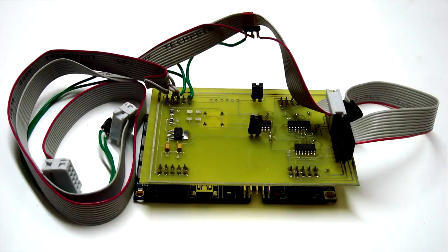Since I had an effective glitch, I took the circuit from the breadboard and etched a simple PCB that could plug directly onto the XMega development board. This performs exactly the same function as the breadboard glitcher, but I'm a bit less likely to accidentally unplug a wire from the breadboard and have to repair things. The circuit was simple enough that I could create a one-sided PCB, so it was very easy for me to etch at home.